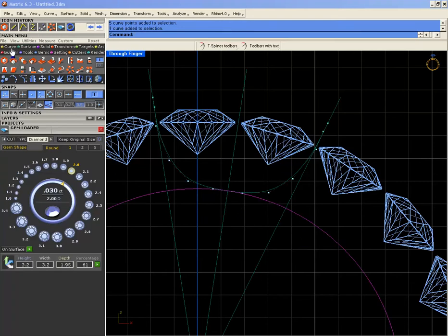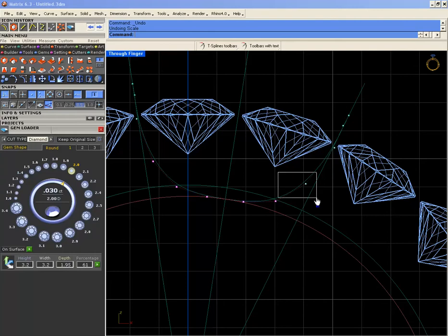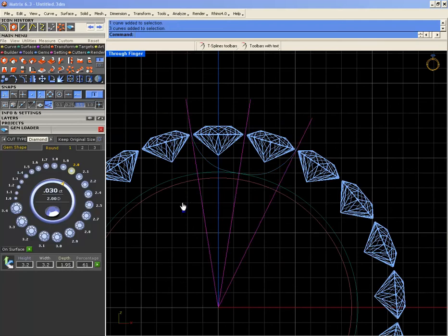Okay, the minimum thickness is gonna be 0.4, so minimum thickness of the prong is gonna be 0.8, so I'm gonna offset 0.4 outside so I get this line on this one. So when I have a thickness, they touch, they don't overlap each other. Yeah, they don't come inside this ring grid. Scale 3D. Alright, okay, let me do a mirror and let me just see if everything is alright. Yes, you can see when I try to do a mirror, the shape doesn't change. Alright, so it's properly symmetrical from both sides.